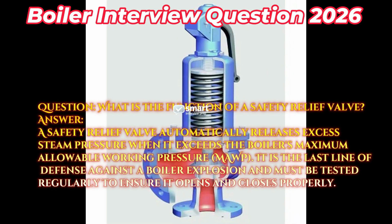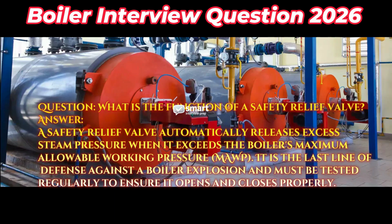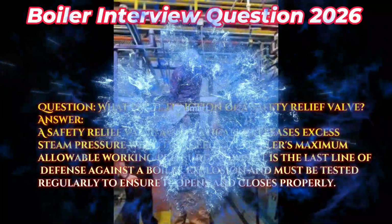Question: what is the function of a safety relief valve? Answer: a safety relief valve automatically releases excess steam pressure when it exceeds the boiler's maximum allowable working pressure, MAWP. It is the last line of defense against a boiler explosion and must be tested regularly to ensure it opens and closes properly.